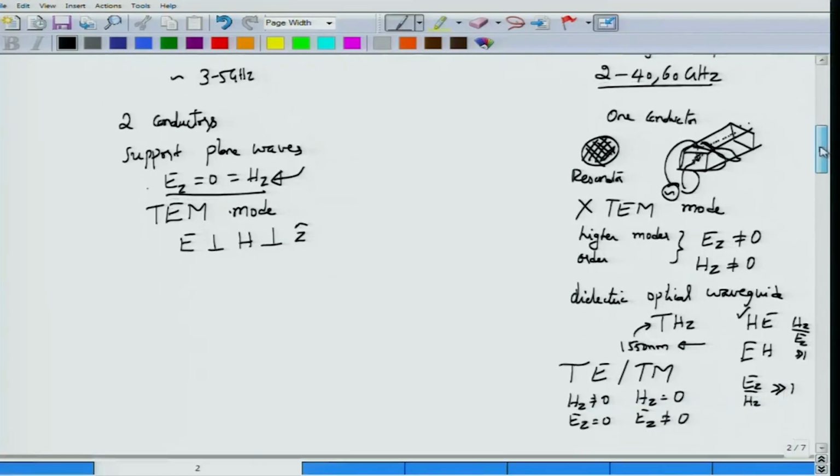Now before finishing this module, let me explain very briefly why these waveguides would not support a TEM mode. Remember, to support a TEM mode, I need Ex and Hy. And how do I get Hy? Only when I have one conductor which is carrying current along the Z direction, which would produce magnetic field lines around it, and these field lines would then form the magnetic fields along the y direction, right. So if you space them apart, they would form the y directed magnetic field, okay.